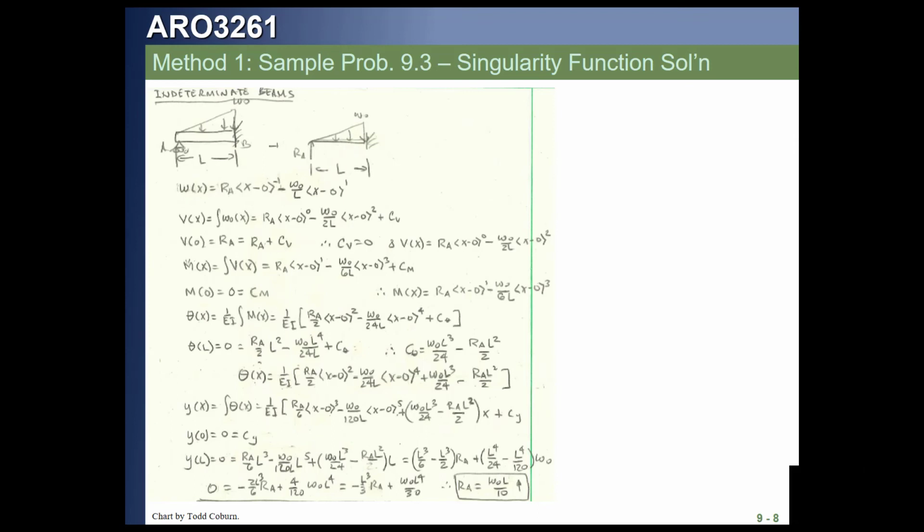And what we're going to do at first is write our singularity function for the loading. We see that the reaction at A, if we assume that's positive, is going to be positive. It starts at x equals 0, and it has a coefficient of -1. For this gradient loading, we put in first the k, and since this is acting downward, it's a negative. The slope of this loading is actually going to be w0 divided by L, so we're going to put that in as our k. It starts at x equals 0, and the coefficient for this kind of gradient loading is 1.